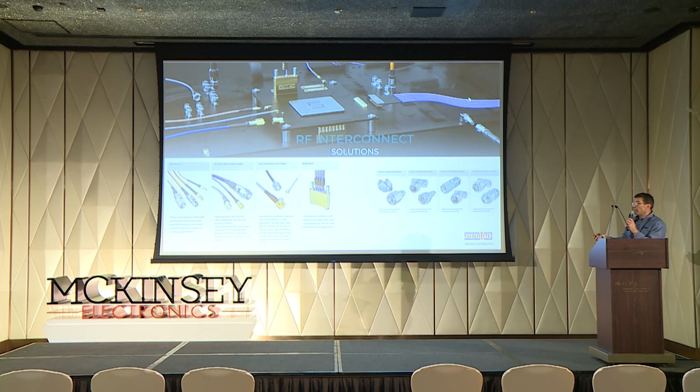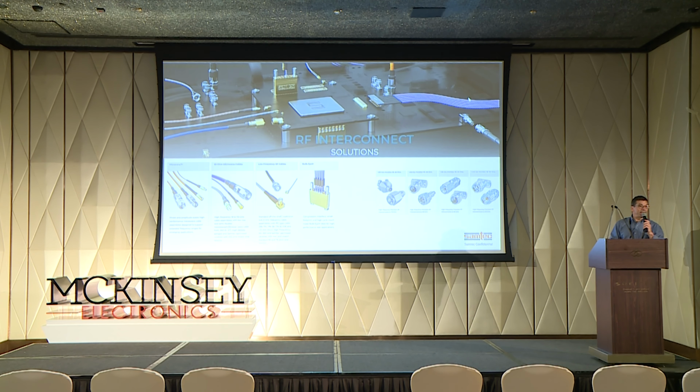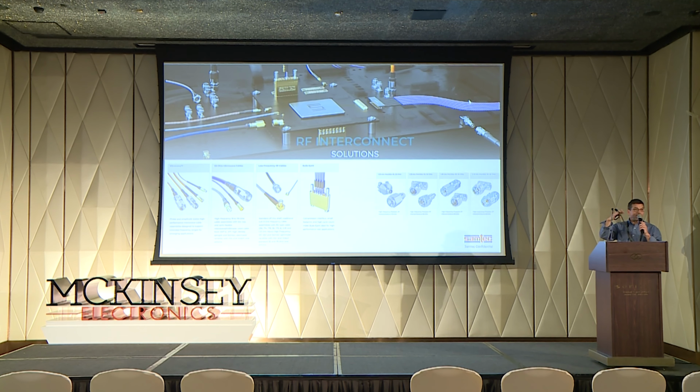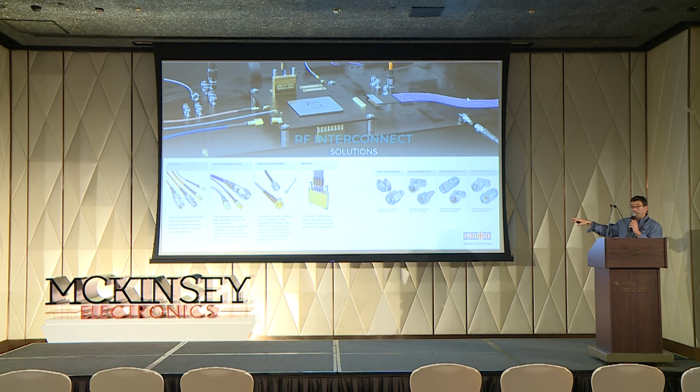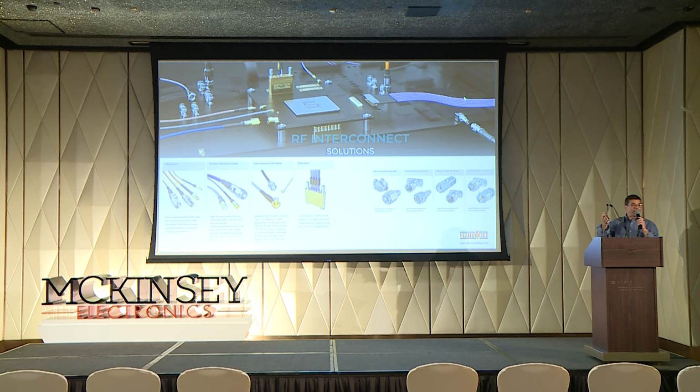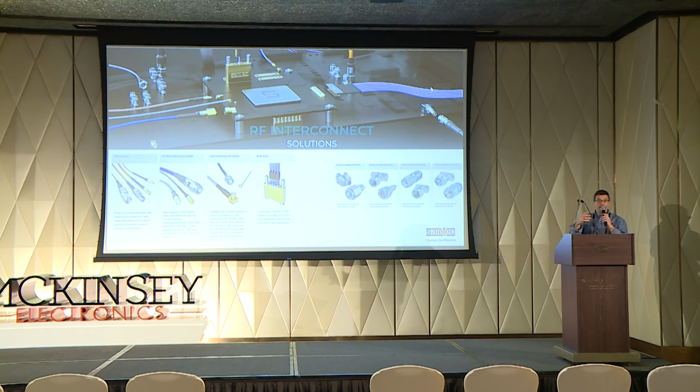And the Bullseyes are RF test points for doing SerDes testing. So if you're breaking out from an FPGA and you come out of the SerDes at 112 gig or 56 PAM4, we'll do a high-density test point going out to 2.92 or 2.4 millimeter SMAs for SerDes testing.